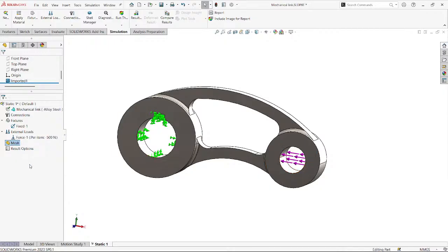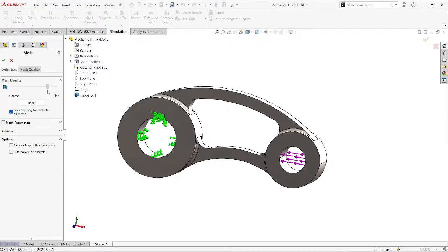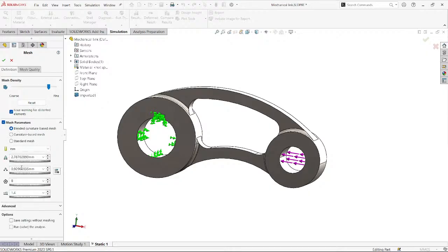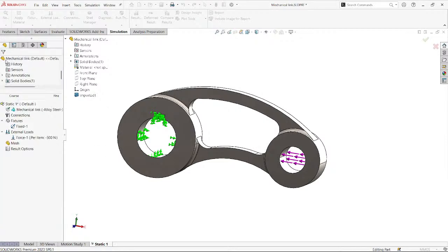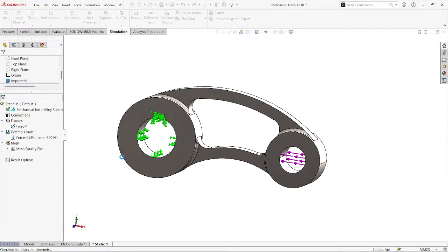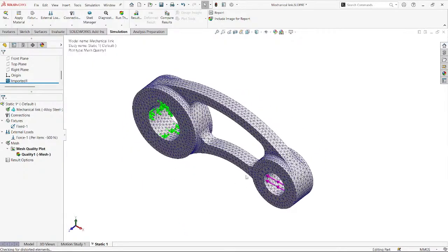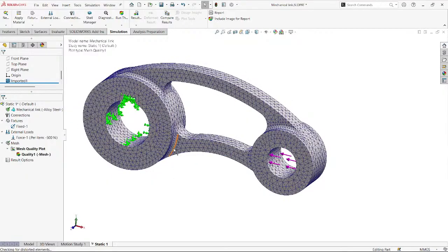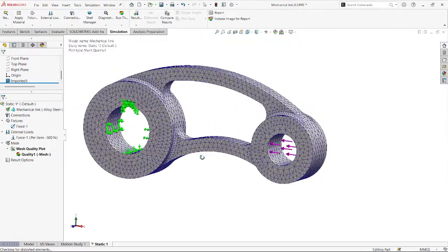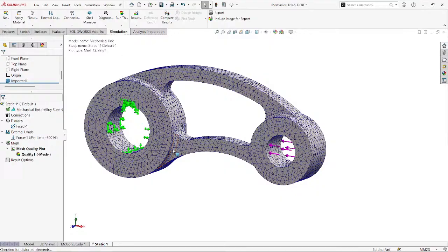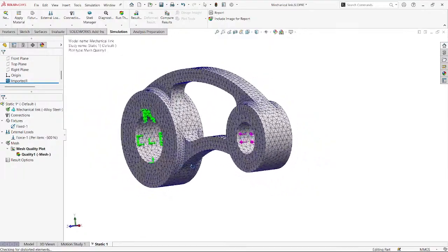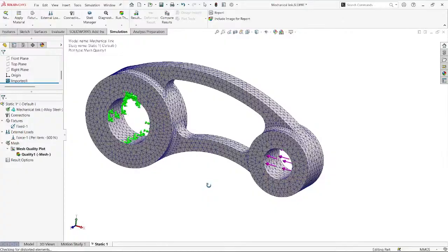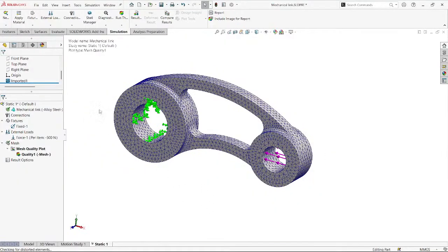Now I'll need to mesh this model. I'll go ahead with a slightly fine blended curvature. This time I would like to use 3. Grain check. So here I do need the curvatures. I don't need to do the geometry cleanup on this model because, due to the buckling or the load cases here, we might get stress hotspots. So we should have the curvature radius there. Now this is fine.